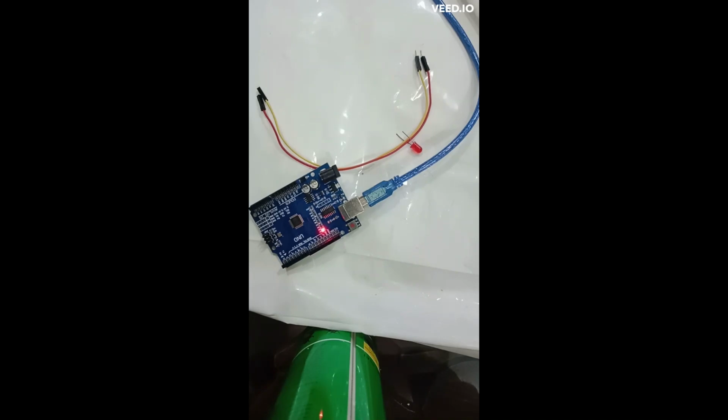In this video, we are going to learn a very powerful feature of Arduino, which is pulse width modulation. With the help of pulse width modulation, you can control the digital output of Arduino from 0 volts to 5 volts. Means you can adjust the output power you are getting from digital out of Arduino. If you want to get 3 volts, you can use pulse width modulation accordingly, and in this way we can play with the output power of Arduino.